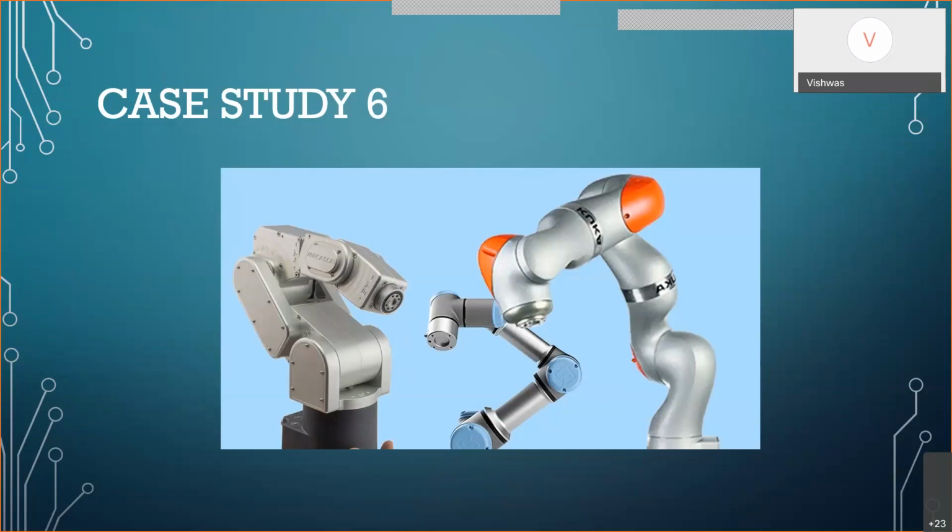But in order to have a precise movement, you'll have to get all the feedback from the sensors. So how do you basically get the information back from the sensors? Let's say you are controlling a motor. Each joint will be there. There will be one joint here, one joint here, one joint here, like that. For each joint there will be a particular individual stepper motor or a servo motor which is being used to control that particular movement without any inertia. What makes the stepper motor or servo motor different is they can precisely stop at that particular point.